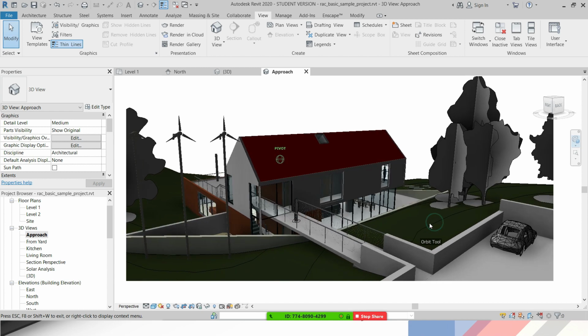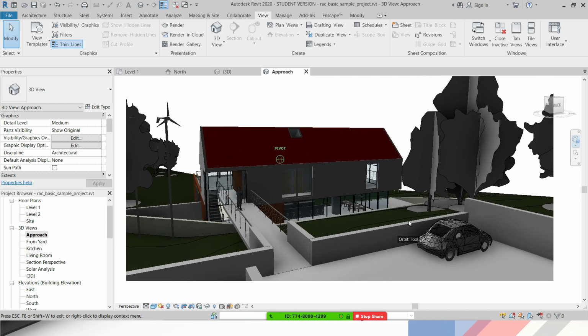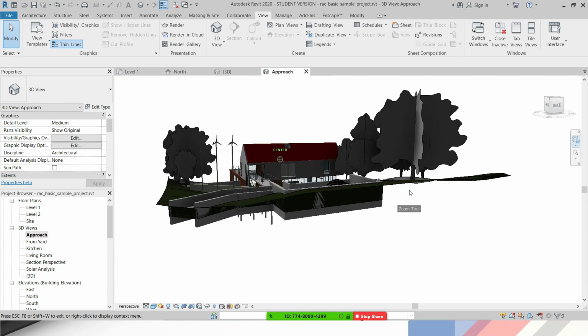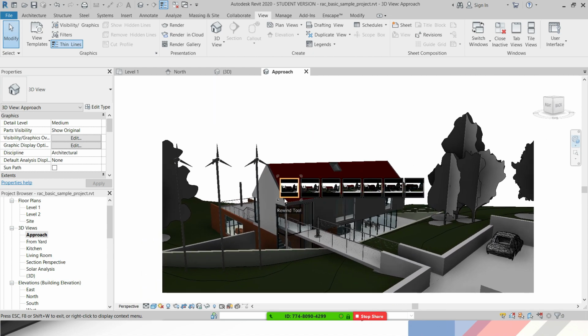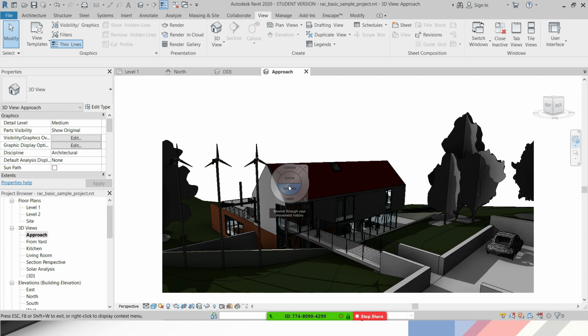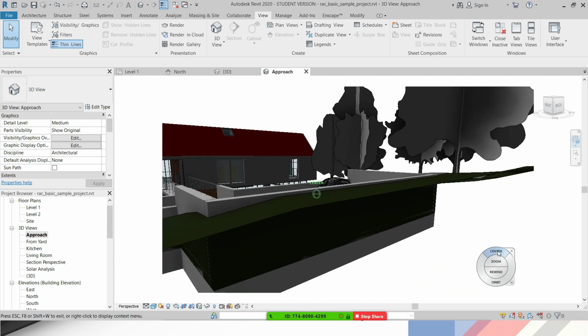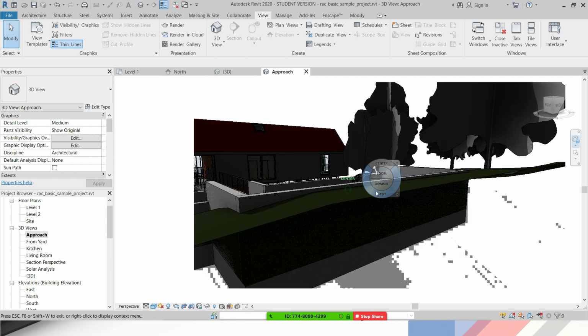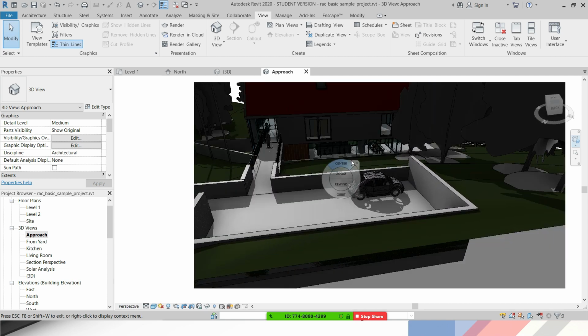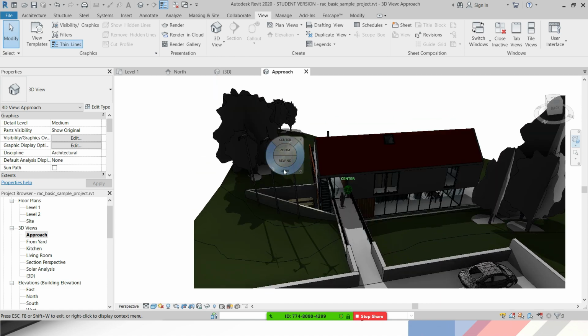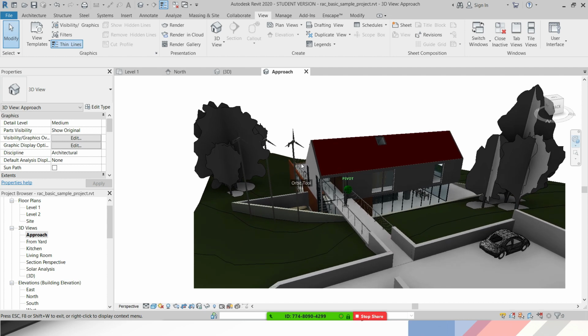You can see here that I can use the same options. I can orbit, I can zoom in and out, and I could rewind to undo all the modifications to my angle. There is another option that is center, and if you click center and move it to a spot, let's say to this car, then my focal point is going to be this car. Whenever I orbit, I'm orbiting around this specific element. To change my target, I'll click again on center, and now I can navigate around this.